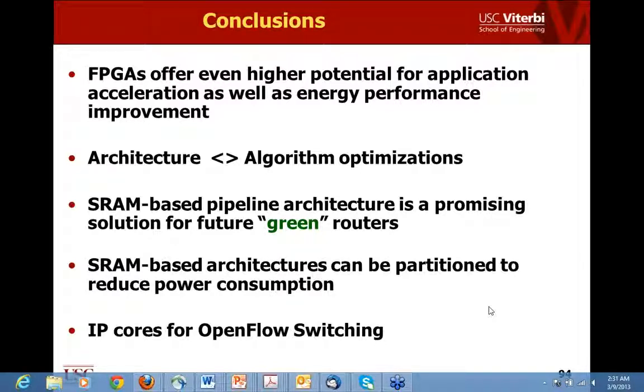Right. Whatever I talked about in the examples, look at a pipeline stage as doing some kind of comparison, deciding which particular path to take in your tree structure, the search tree that we have. Therefore, each pipeline stage is very simple: it gets the input, maybe a 16-bit or a 32-bit number, and compares it against a key stored at that stage by accessing the local memory, and then forwards to left or right by computing the next address to be used in the next stage. That's a simple pipeline stage.